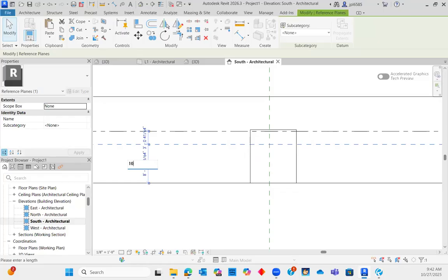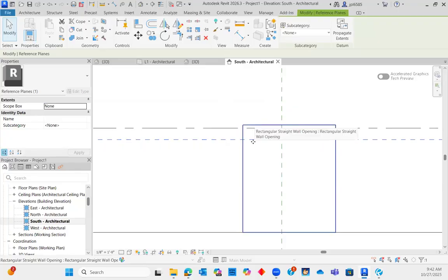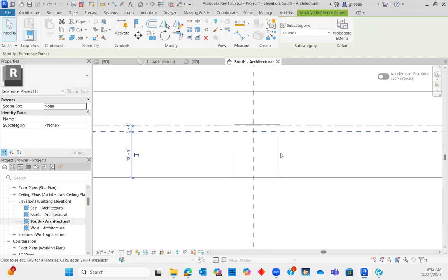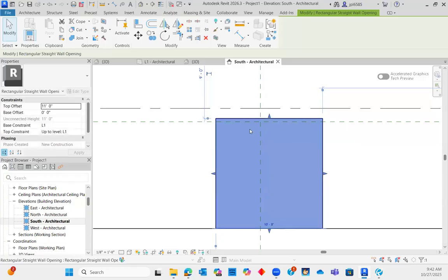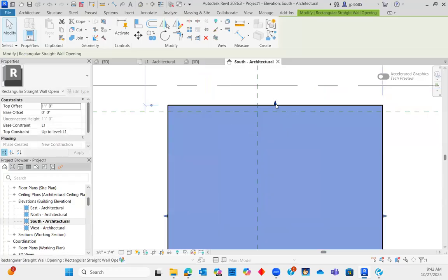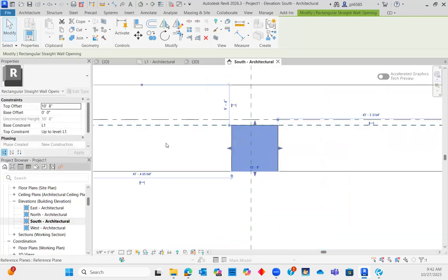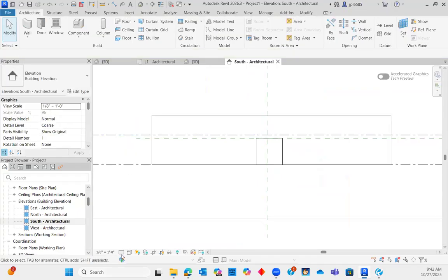It's something that you can draw and you can later lock to, like if you wanted to draw to a certain height. Like in this example, I want to adjust my wall opening. Because it wouldn't let me adjust it with numbers, I'm just going to lock it to my reference plane, which I set at 10.8. So now I know my wall opening is at the correct